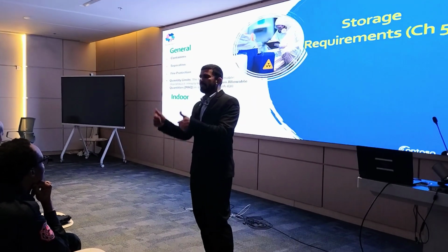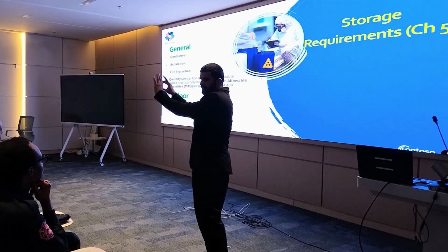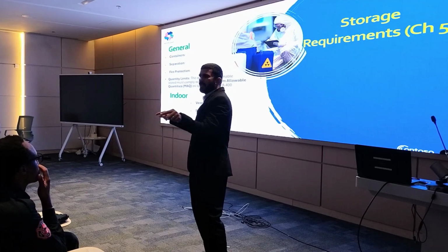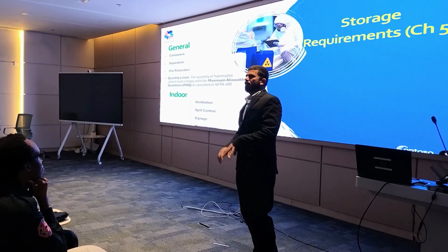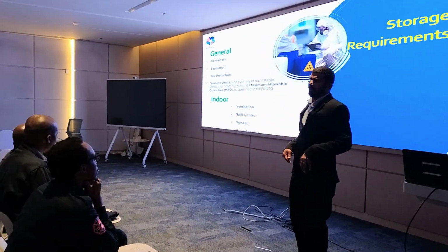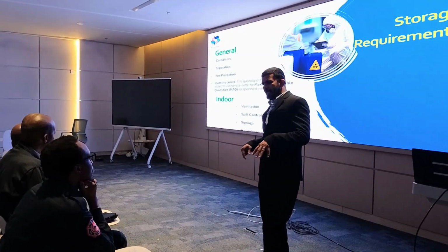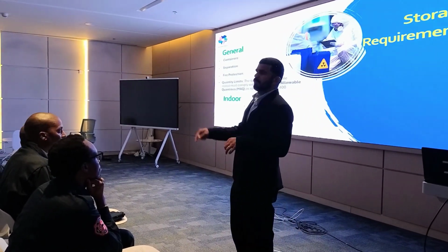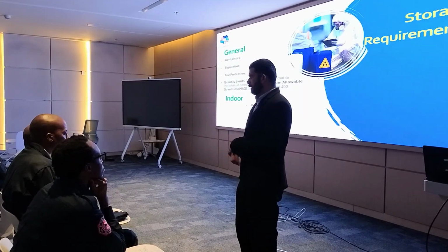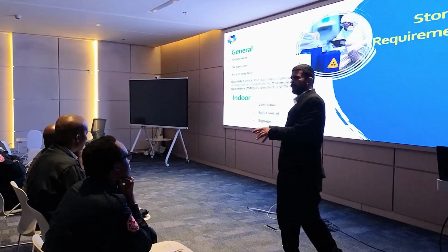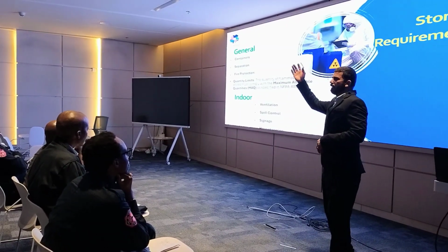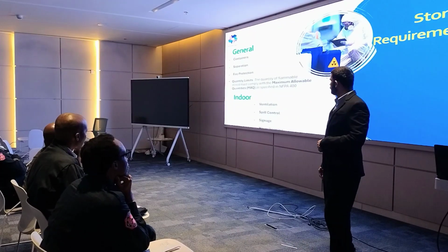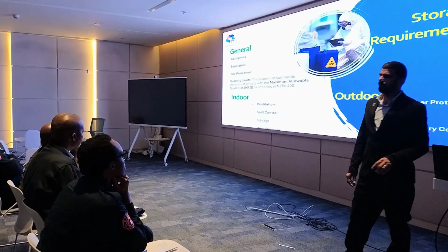Signages. We put the signages also. This is a flammable storage. Do not go, no area for visitors or for any other person. And the last one is housekeeping. We have a complete team of housekeeping that does housekeeping of that area. If anything is spilled or found, they should inform us and we can clear out that area. This is for indoor storage. You can store in our warehouses or indoor containers, or in a store like this. What about outdoor storage? What is the requirement for outdoor storage, by the way? Simple.